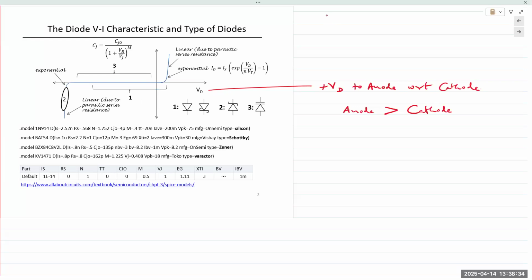So of course, unlike a resistor, there is a small portion of the diode where it doesn't turn on, it doesn't conduct current at all. So it's 0. We've all looked in chapter 1, we saw why that is. And then it rises slowly as the diode voltage is progressively increased. After a certain point, the voltage is sufficient to overcome the built-in junction potential. And from that point on, the diode starts conducting. So that's the linear region right there. Okay. So again, non-linear device.